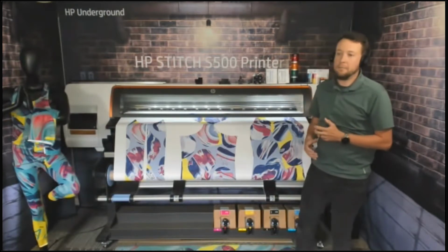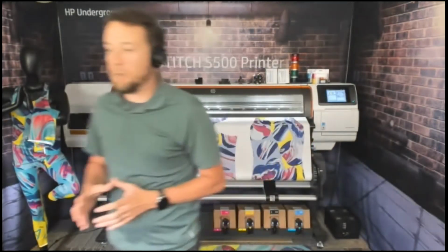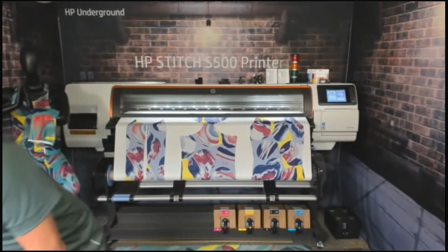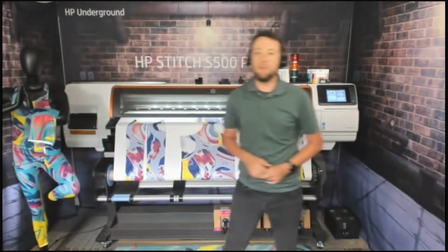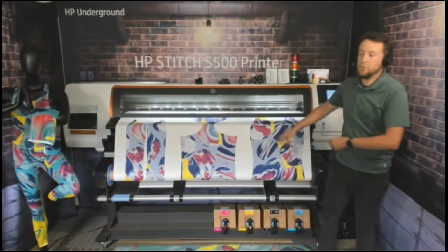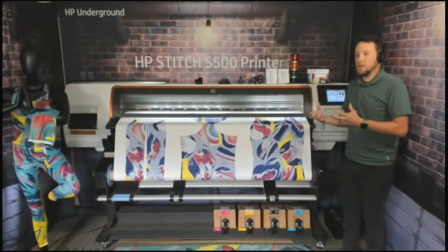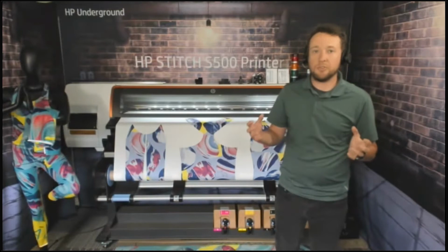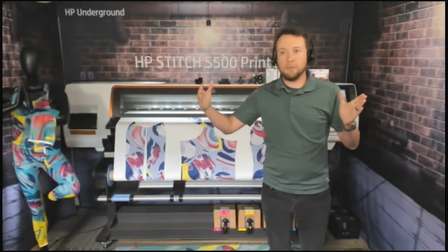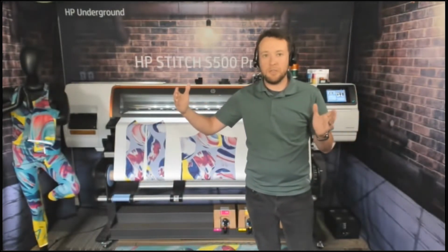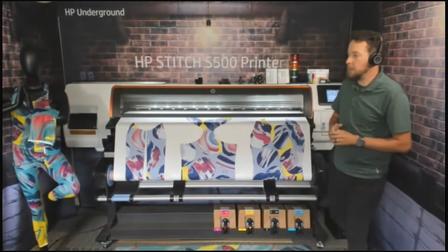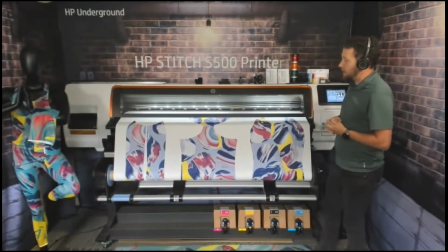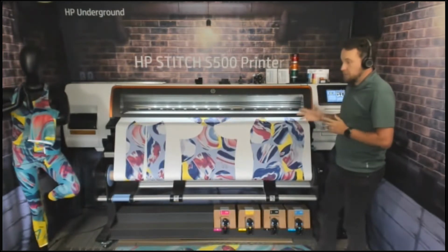Take-up issues can be a nightmare in dye sublimation, especially in the transfer in the calendar part. So if you have a lot of issues on your take-up here, and you go to calendar this, it's going to have a lot of problems during the calendar process because it's not taken up evenly across, or you may have some stair stepping or some walking on each side of the take-up. But being able to add the heat in the print zone gives us high image quality.